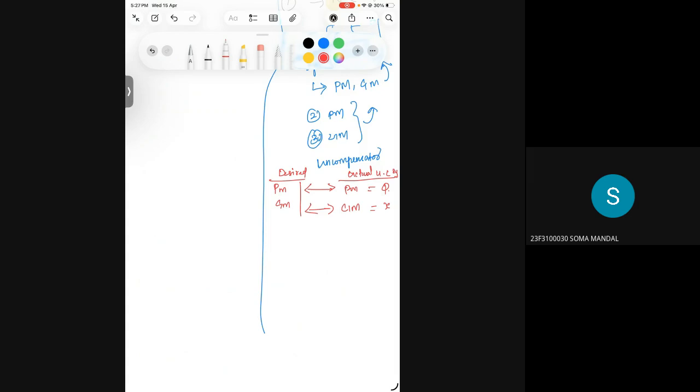Okay. Fine. Once you find this, the next step is to calculate the compensation. What to do to make this compensation work, or what to do to solve this deviation between the actual and the desired. For that, for your lead compensator, the first formula you can try is phi m, to determine the amount of phase angle to be contributed by this lead network. That's what we are going to do using this formula, where phi m we call the maximum phase lead angle.